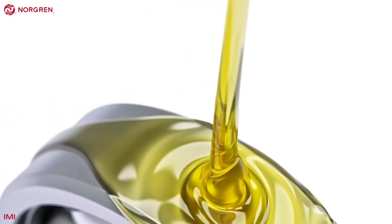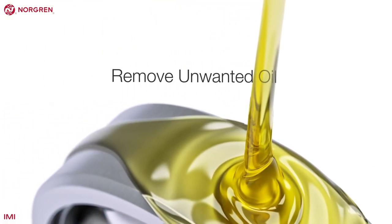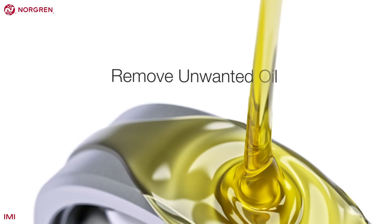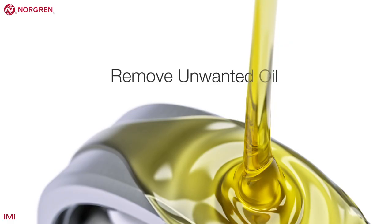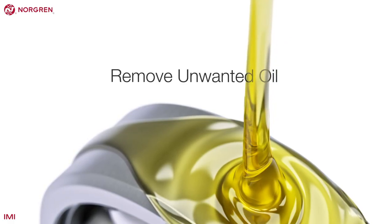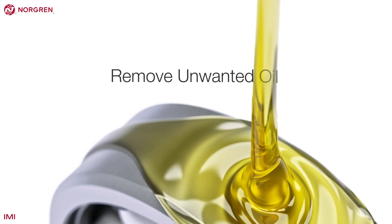As well as removing water, we need to remove unwanted oil, usually from the compressor. This contamination can cause issues itself, but when mixed with moisture, it creates a substance that isn't good for lubrication and can stick to moving parts inside pneumatic components, slowing cylinders, for example.